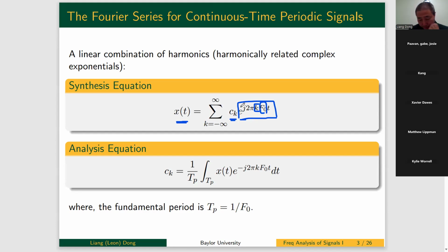So add them together. In this case, you will find out these sine waves, what I put in the box, are actually discretized in frequency. I have f0, which is the fundamental frequency. I have a 2f0 sine wave. This is the frequency domain, but weighted differently. This is weighted as C0. This is weighted as C1. This is weighted as C2. And add them together.